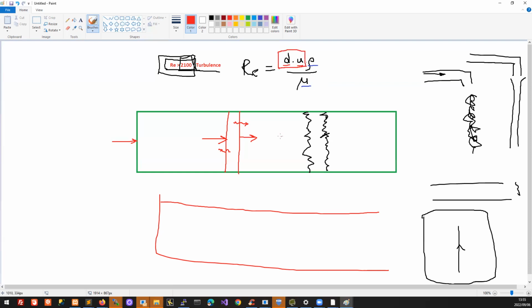So that's one of the tremendous advantages of using dimensionless groups. You could think about trying to solve this. Imagine the complication of trying to model or simulate even turbulence like this. And there are attempts to do that. But it's going to be so complicated to try and model every single packet of fluid. Instead, you have this nice practical Reynolds number, which immediately tells you whether it's going to be turbulent or laminar. So that's a giant step forward.